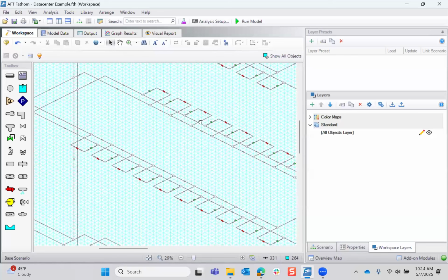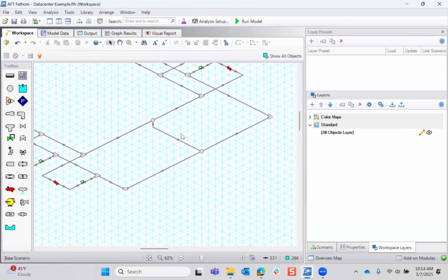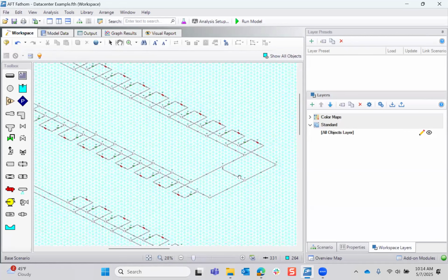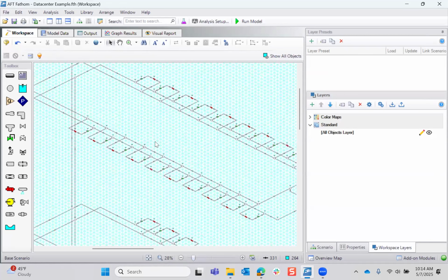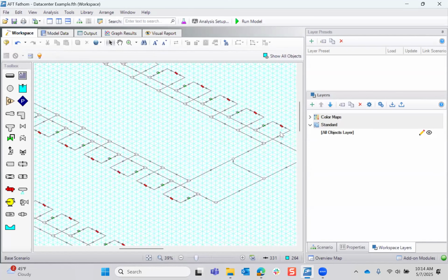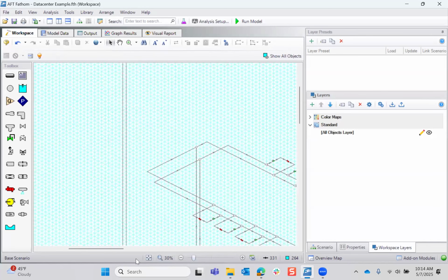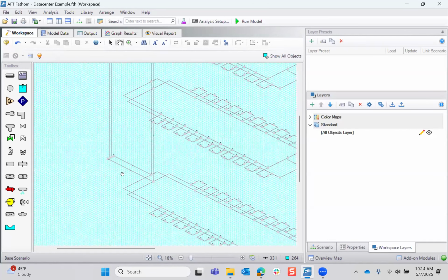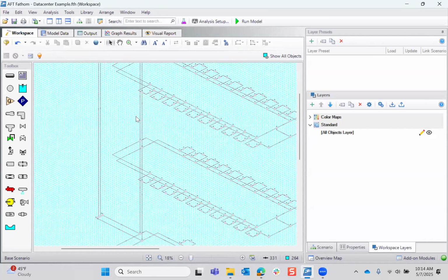So in order to mitigate that, I also added this line connecting the remaining flow that makes it past all the heat exchangers back into the line. There's kind of two advantages of that, which was one, you can have more stable pump operations, and two, you're also looping back in some of the cooling water that you've already cooled back into your hot line, so the chiller doesn't need to do as much work at the bottom. So with that, we can hop into results.